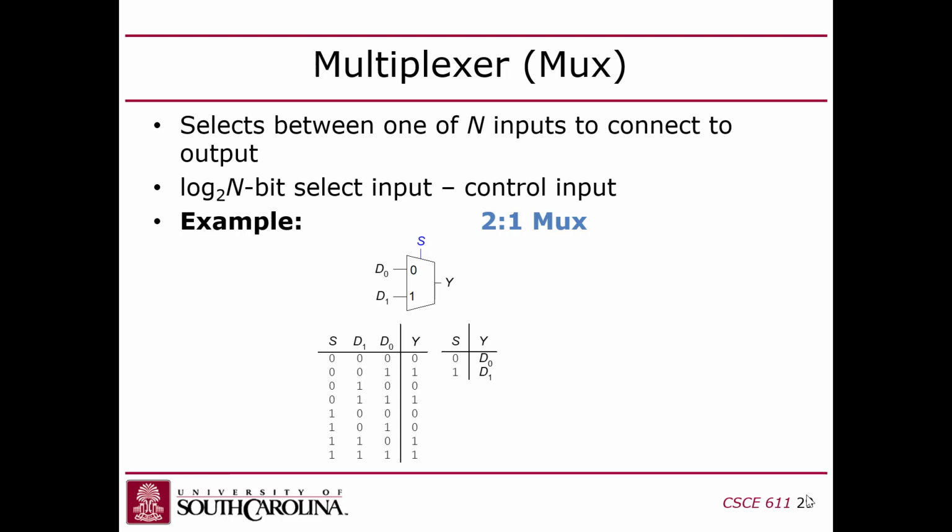But if I do a load instruction, I want to pull something from memory and put that in the register file, right? So I have these 2 values that I potentially may want to put in the register file. So you're going to drop a mux in there in front of the register file that will allow you to select what you want to write into the register file, right?